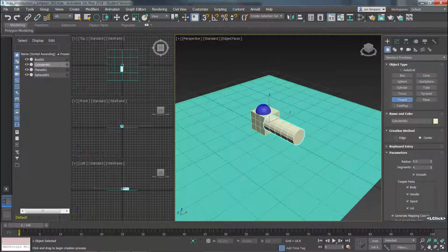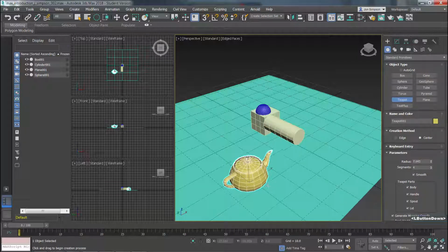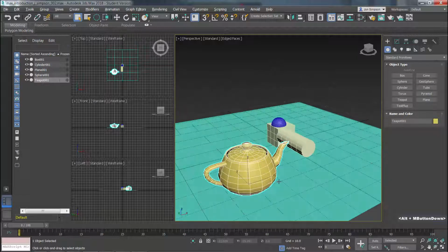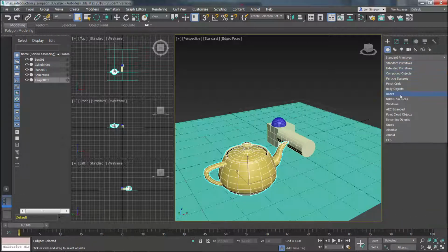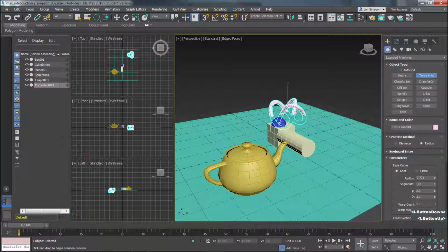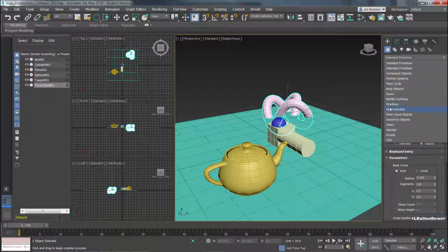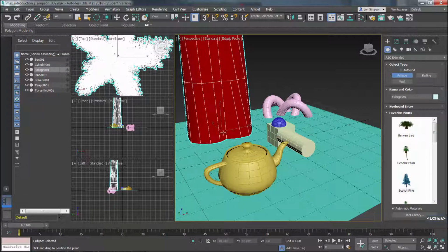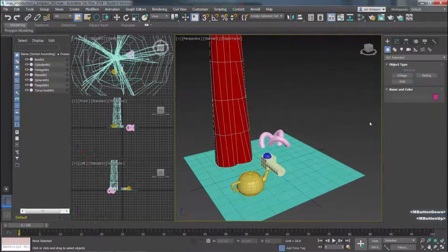This allows for the quick creation of objects with the correct spatial orientation. No discussion of standard primitives in 3ds Max would be complete without mentioning the Teapot. Seems an odd thing to have here, but there's a reason it's here, and a quick Google search will tell you why. There are many other types of objects that can be created. Click on the drop-down that reads Standard Primitives to reveal more objects. Extended Primitives has more complex basic objects like torus knots. AEC Extended has prefabbed walls, trees, and more.